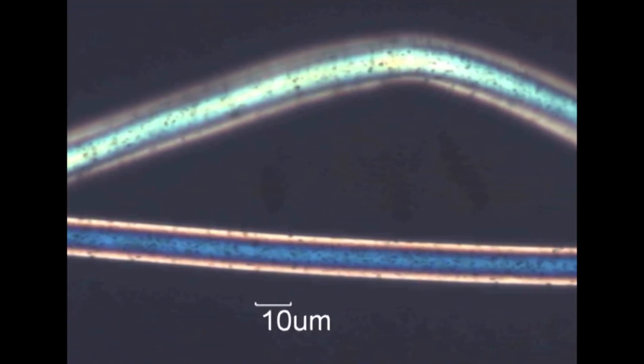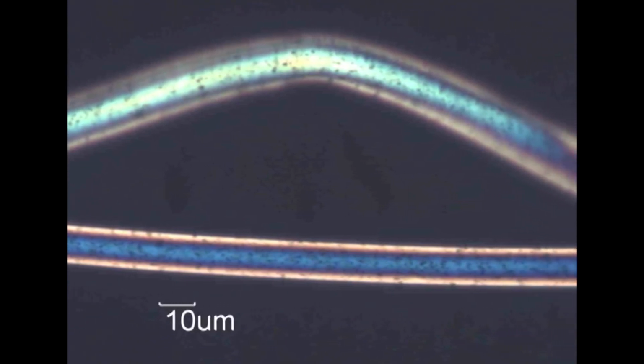a black spotted effect, and when you see the fiber under a microscope, you will find that there are black spots. And so when the light ray falls on the filament and the black spots over there, the titanium dioxide will absorb part of the light ray and reflect only part, and thus the amount of luster in the filament can be controlled by addition of different percentages of the titanium dioxide.